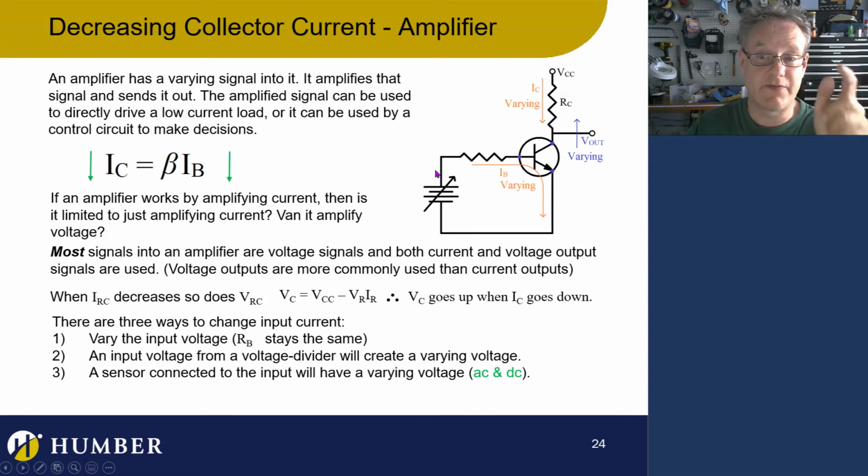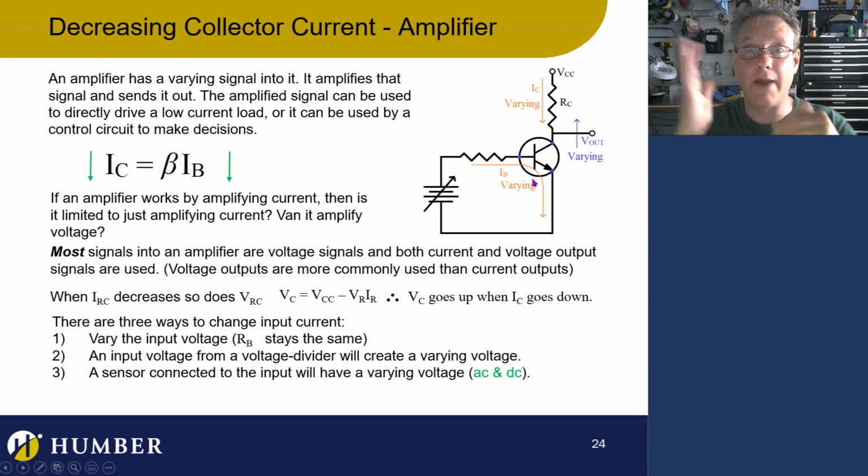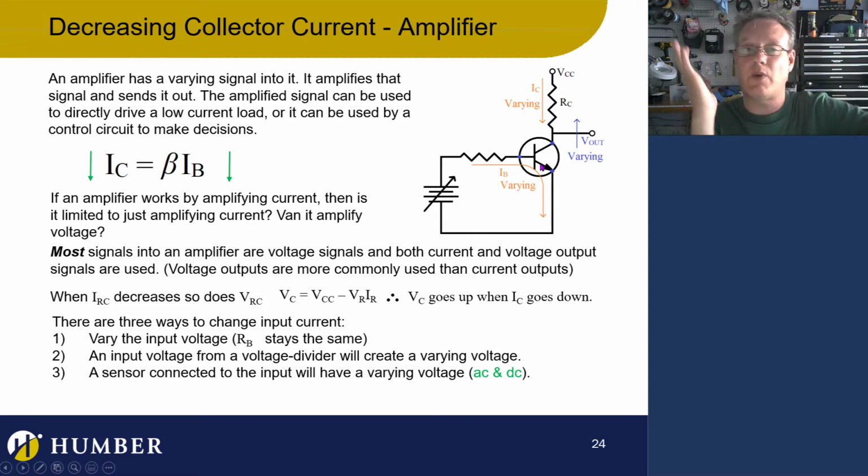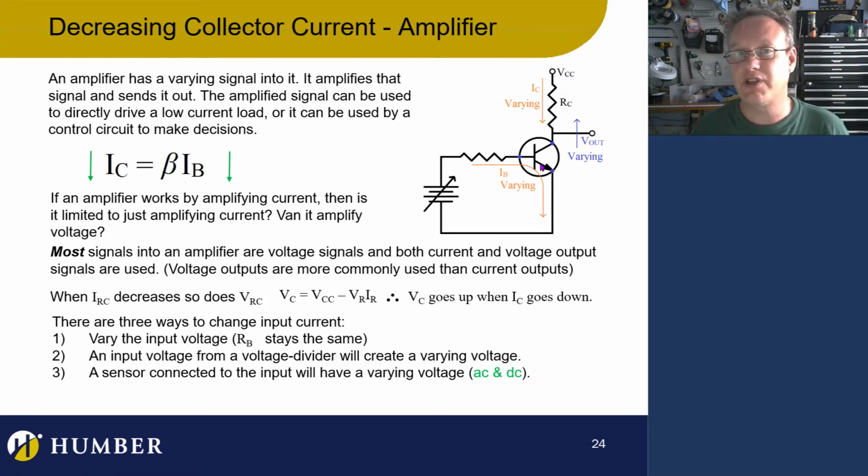What I want to say is this. If I put 0 volts here, there's no current. This BJT is wide open. What's the voltage at the VCC? Let's say the VCC is 10 volts. What's the voltage V out? Again, I've got 0 volts here. There's 0 current going through here. This is a wide open switch. If I study the voltage at V out, it'll be equal to VCC. So if this is 0 volts, this is 10.